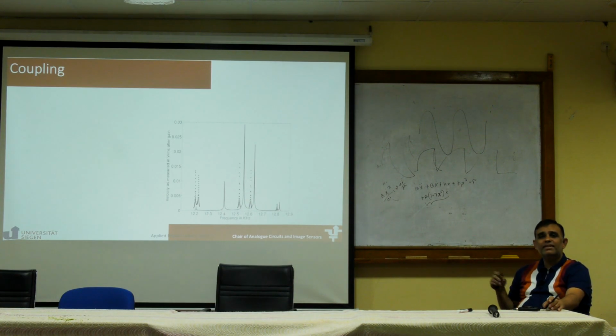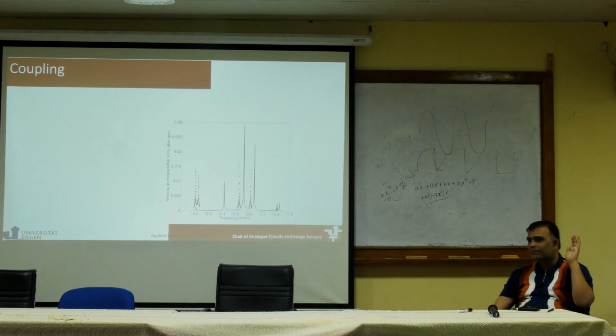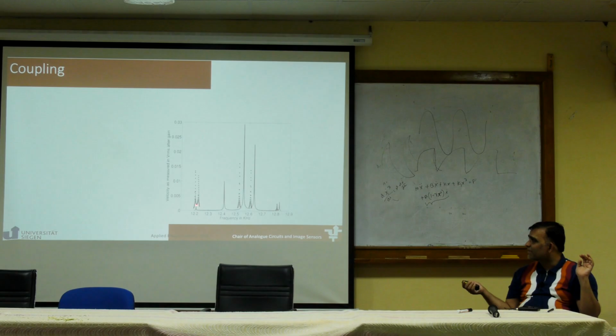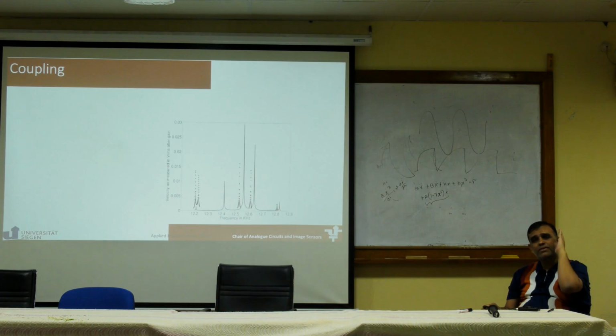So when we change the third resonator by putting a small mass on it, and we are still measuring only the first resonator, we are not measuring the third one at all, the frequency response of the entire system shifted. This one did not shift by much. This one shifted by a large amount. This one shifted here. This one shifted here. So just by looking at the frequency response of the first resonator, I can tell which one of these resonators has shifted.